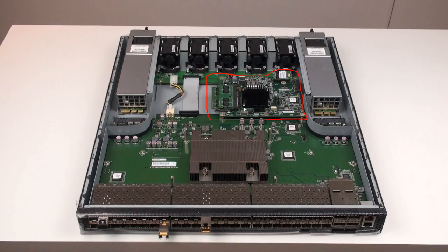And this is completely modular, so it's actually a complete embedded PC. Underneath this heatsink, it's just a microprocessor. It can be Intel, PowerPC or some kind of ARM processor. It has RAM, it has flash, and it has southbound interface drivers for PCI Express, which connect it to the main chipset. Also, it has something called I2C, inter-IC communication, which manages the other chipsets on this motherboard.